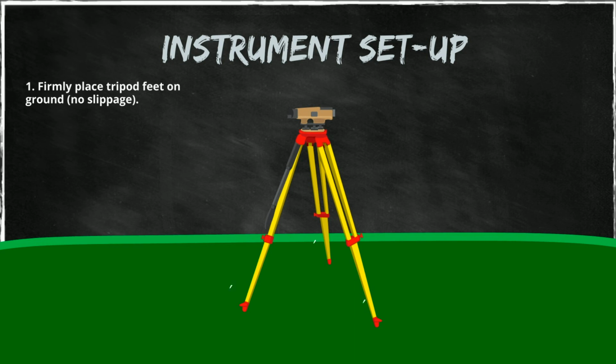Then the feet of the tripod are sharp, so they will easily find a spot on the ground where they don't slide around. That is very important. If one is on soft ground, then some surveyors will step on this ledge and push the tip into the soft ground to firm up the position of the tripod.